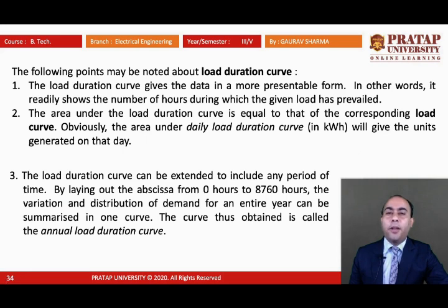The following points may be noted about the load duration curve. The load duration curve gives the data in a more presentable form. In other words, it readily shows the number of hours during which a given load prevailed. The area under the load duration curve is equal to that of the corresponding load curve. The area under the load duration curve gives the units generated on that day. The load duration curve can be extended to include any period of time.